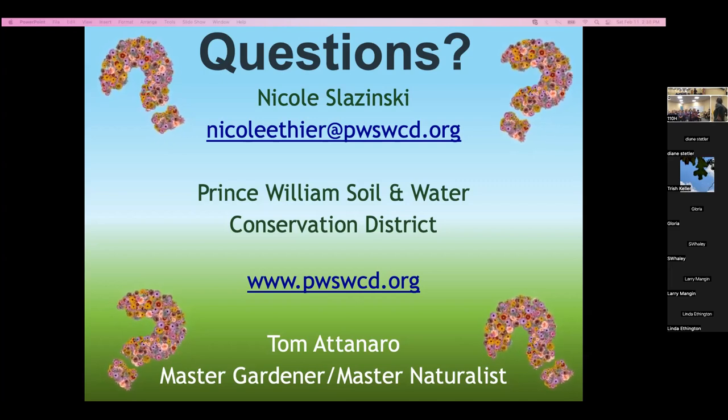At that point it becomes almost like a drainage ditch. But for both of these situations, couldn't you also put a rain garden upslope from the wet part to capture the water and slow it down? You can. Also, on large slopes, anything you can do to interrupt the water flow helps, like plantings or crosswise ditches, water bars or something like that.